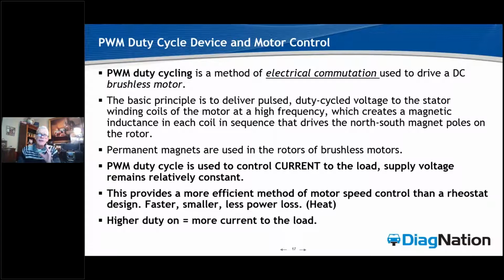And guys, if you're taking notes right now, please, I told you to study transistors, study inductance. It is of the utmost importance to understand solenoid and coil operated circuits as well as this motor control, inductance, okay? That's what is being used for AC-like operation of a DC permanent magnet motor. And what it's going to do in the case of three-phase is it's going to pulse that current into the motor at 120-degree intervals to pull magnetically the motor around in a smooth, powerful circle.